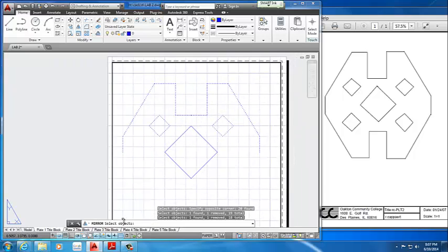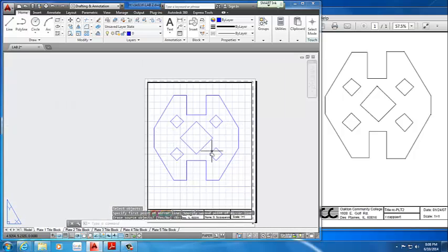And it's going to ask you, select objects? No, I'm done for now. 18 total, that's right, because I had 9 in the beginning, times 2, 18. So I'm just going to click enter or space. Now it's going to ask me to create a mirror line. This time we're going to mirror it horizontally. So just like that green line you see right now, that's how we're going to draw a line. We're going to start from here, from this point, to this point. And click. Now next option, erase source object. No, N is defaulted, so we just click enter. And that creates our object. So now you're done, so save your work, and you're ready to start a new project.